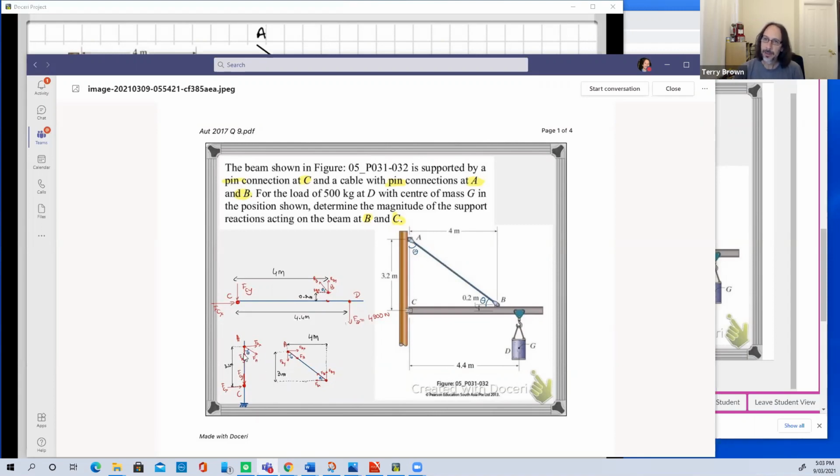Over here at the post, you can imagine this cable is being pulled down by the beam because of the weight. This cable is pulling down on the post. Yep, so over here, that's correct. Right? The cable is pulling down on the post. But on our cable, we should be seeing equal and opposite, because you can imagine that this cable is in tension, yeah?